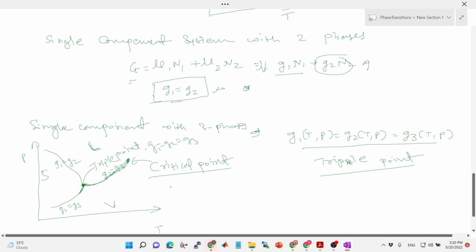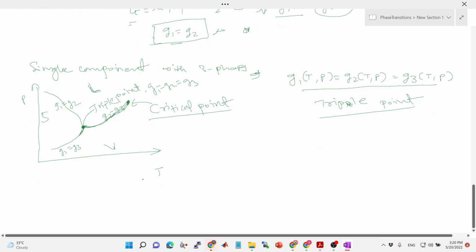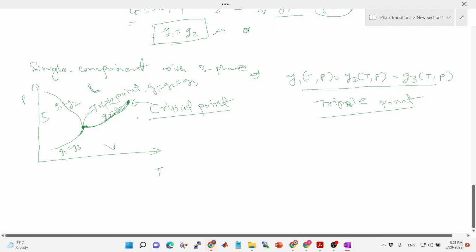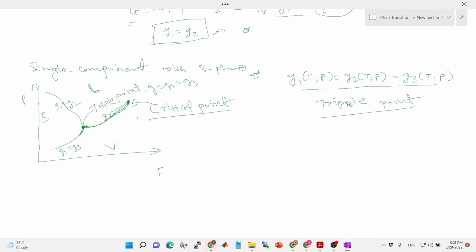So very often this critical point is utilized in the fabrication of electromechanical devices where you have a suspension. When you have your device in liquid and you want to take it out, a huge force will be acting from the surface tension of the liquid, which might not allow you to fabricate the micro electromechanical devices which are suspended, and they can collapse because of this surface tension.